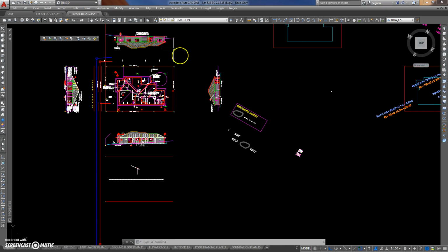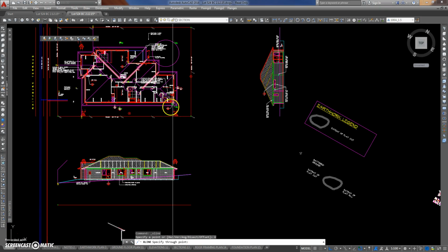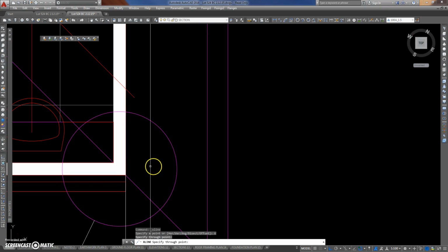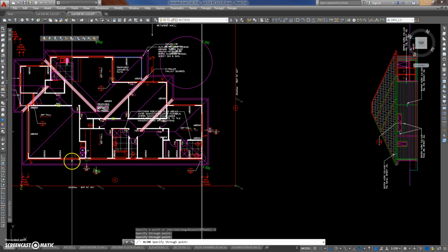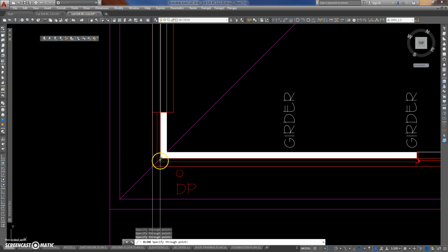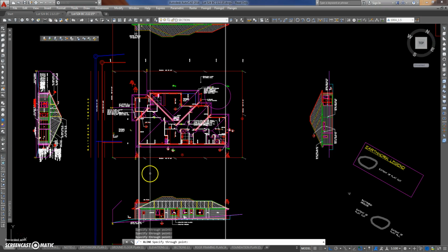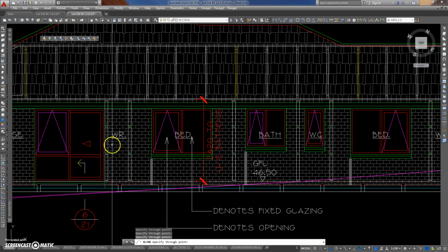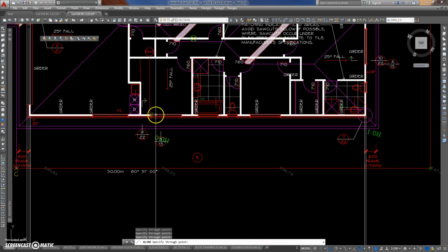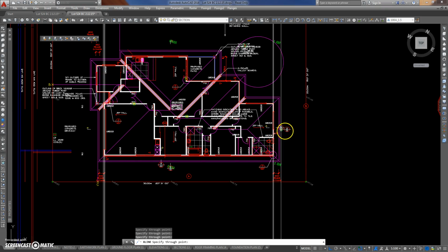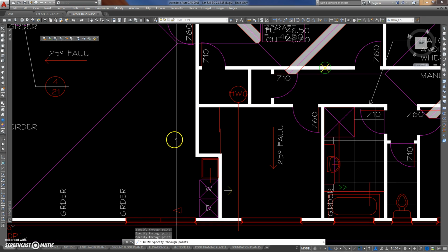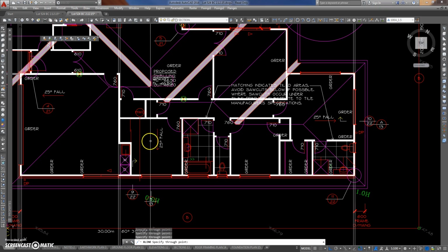So to do this, we use the draw command, construction line, and at the moment it says X line, horizontal, vertical, angular, and so on and so forth. What we want is the vertical. So we can put construction lines through the important points. So we go there and there and so on. Notice down in these sectional views they show the interior walls, so we should really be thinking about the interior walls. See that line through there, that's our sectional line, so we bang in those lines.